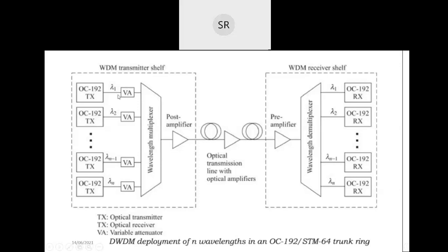That wavelength has a separation of 1 nanometer, or below 1 nanometer, and then they are combined. That is called wavelength multiplexing, and that is called dense wavelength division multiplexing. It means we are combining a large number of channels. We say that the S band and the L band are both combined together and transmitted. That is about dense wavelength division multiplexing, and this example